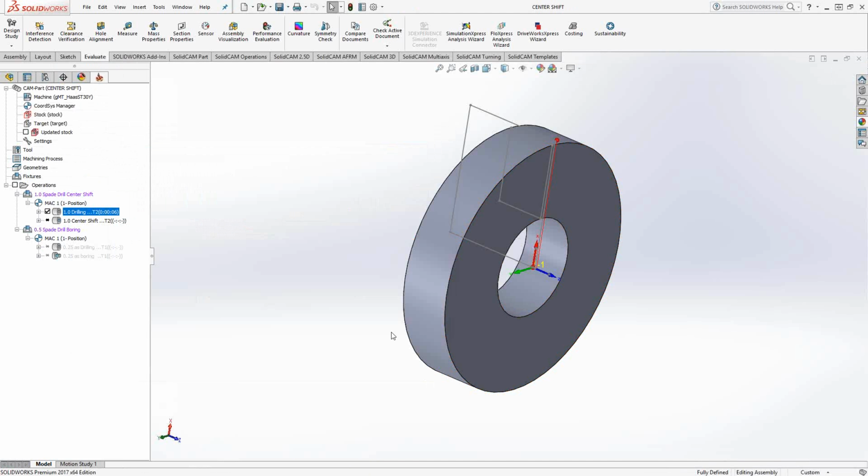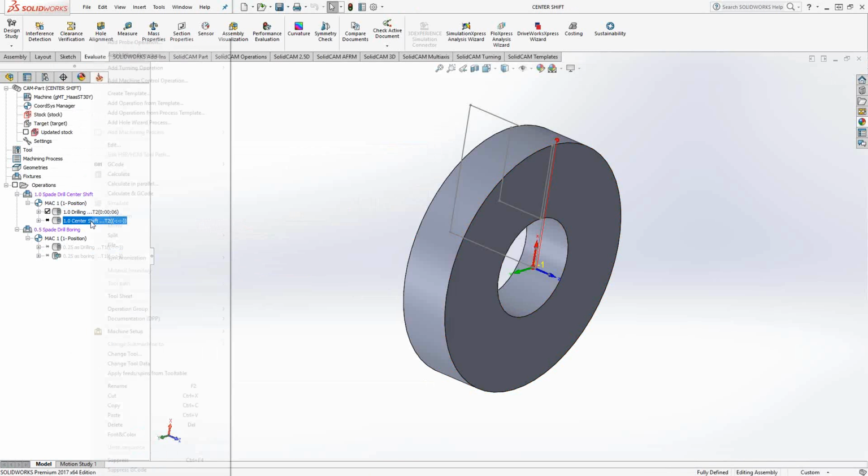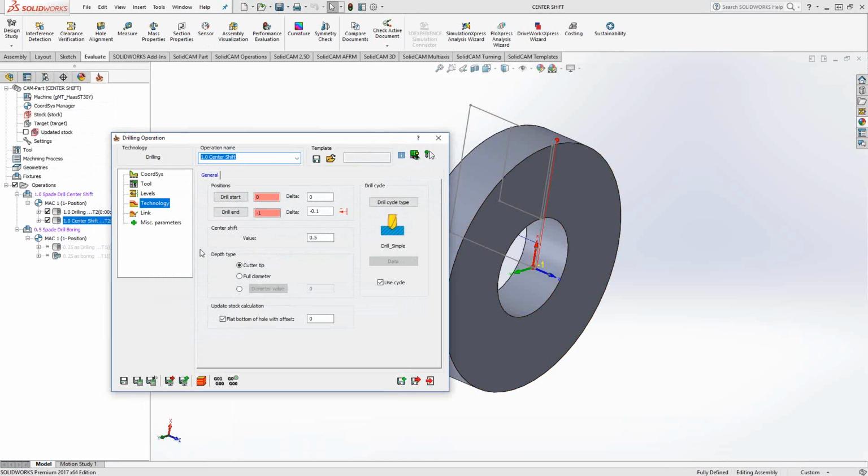It can do some internal turning, because the size of the drill is basically close enough that I can use a function here called center shift. Center shift is essentially just shifting off of the original drill axis. So in a turning drilling operation, we go right down the center of the part from X0 all the way inwards. Now, with the center shift, we actually shift it in that X direction slightly.